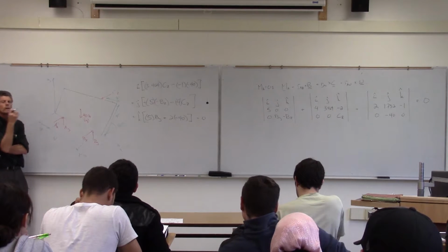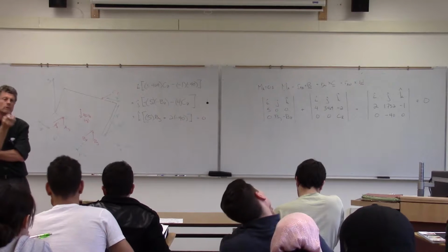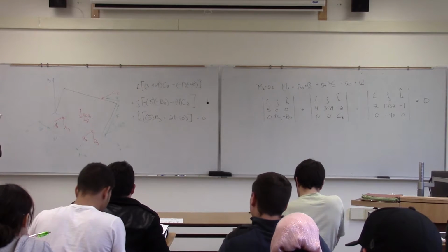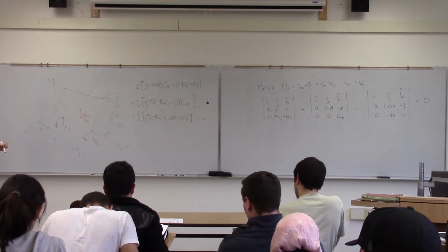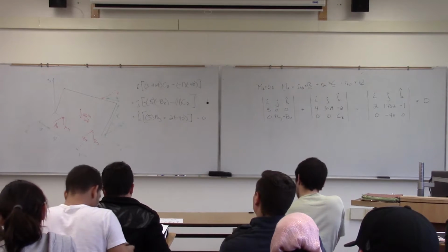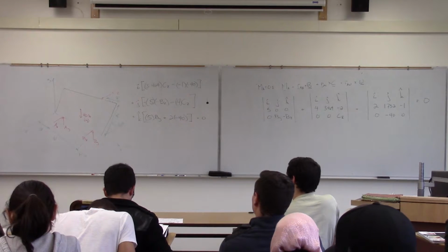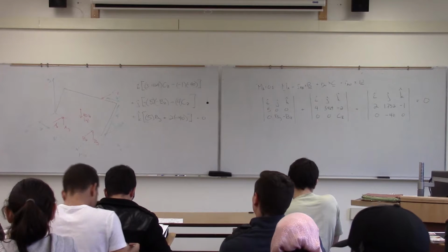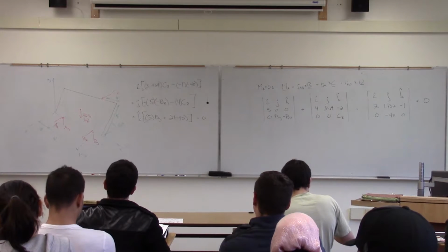So, yeah, when we get into trusses and that sort of thing, one of the rules of thumb in terms of thinking about symmetry is it has to be a symmetric structure and a symmetric loading. So you've got to look at both pieces before you can assume a symmetry or a BZ equal to AZ and that sort of thing. So this would give us a reaction at A. We have to do it again 2 more times for B and for C.